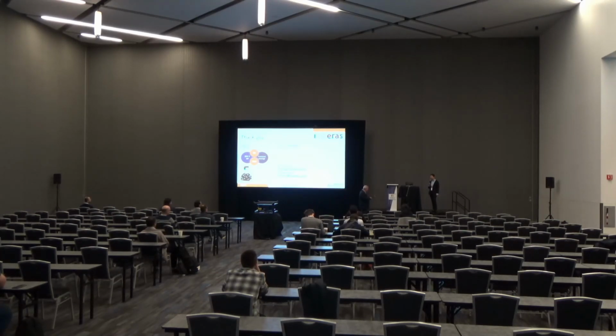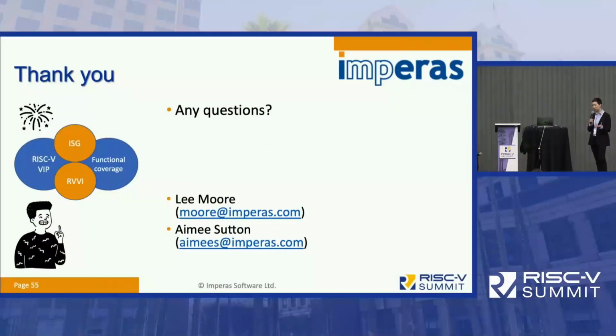Yeah, I think if that's what we're talking about, it makes sense to take a complex piece of logic, like Lee referred to, the vector processor, and verify it in isolation. If possible, it's good to use a similar approach to what you want to use for your entire processor so that you can make some reuse of maybe some stimulus drivers that you've written in order to stimulate that. Yeah, at least use the same language and the same general approach.